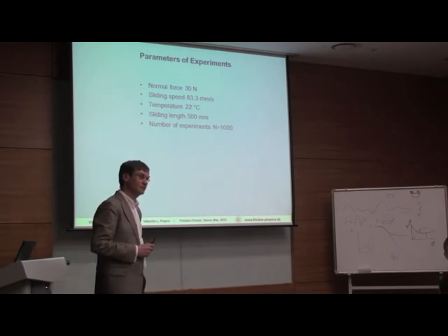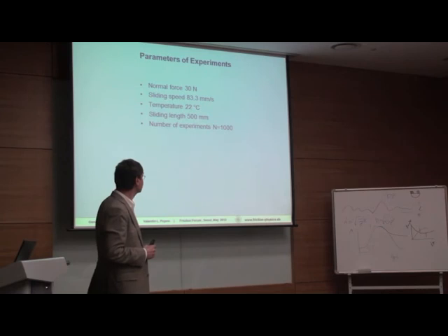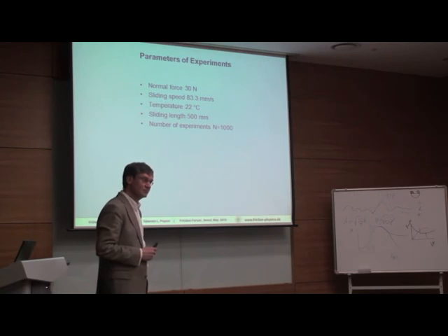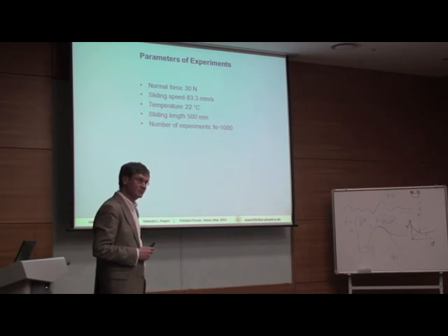It's going over half a metre, and so what you've got there is something in the order of, if you divide 500 millimetres by 80, that's 4 seconds. 8 seconds is the whole cycle time, something in that order. So it's plenty of time to lose that heat that you're going to put into there.